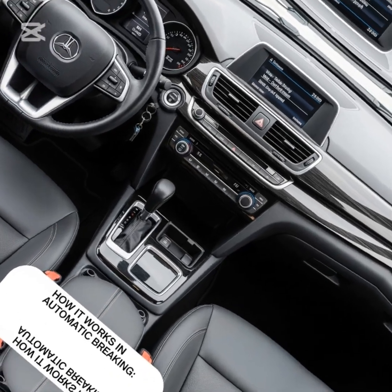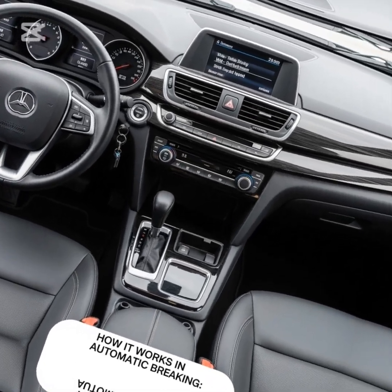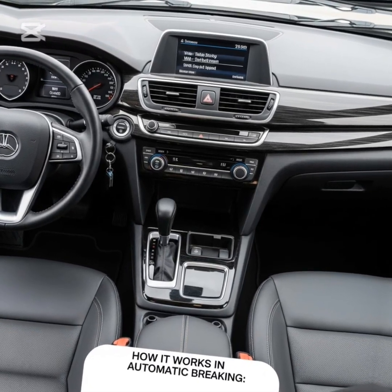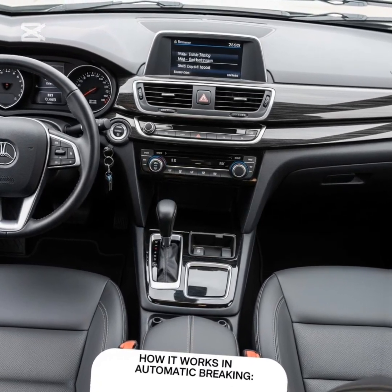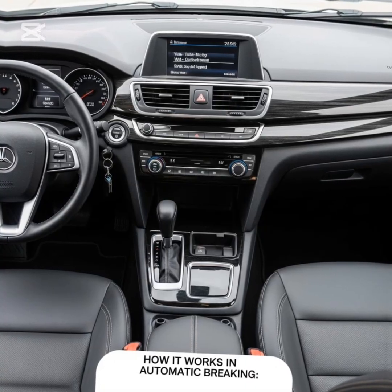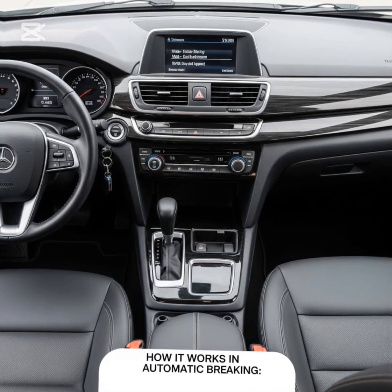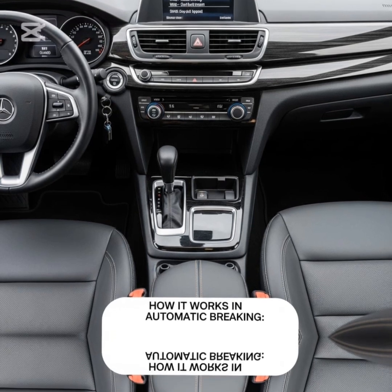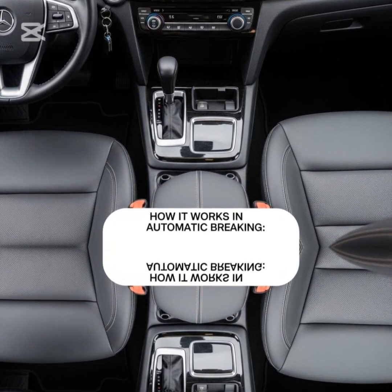Methods of engine braking include shifting from D to L or 2, using paddle shifters if available, releasing the accelerator early. Modern automatic transmissions provide some engine braking automatically, but manual selection increases effectiveness. Engine braking is a critical skill for safe speed control on slopes and mountainous roads.